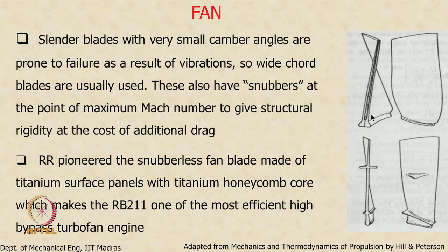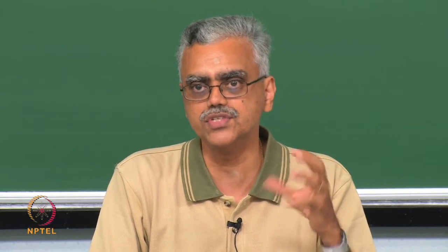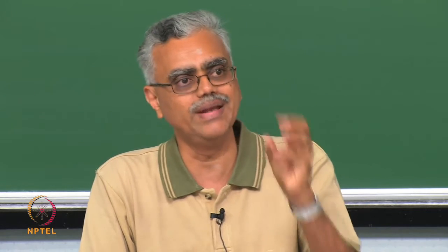The strength comes from the fact that the blades are made out of titanium, but they are not made out of solid titanium. It is actually made out of a titanium skin with a hollow core inside, which is filled with a titanium honeycomb matrix.